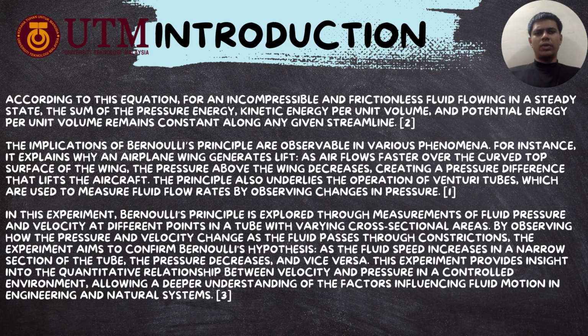According to the equation, for an incompressible and frictionless fluid flowing in a steady state, the sum of the pressure energy, kinetic energy per unit volume, and potential energy per unit volume remains constant along any given streamline.